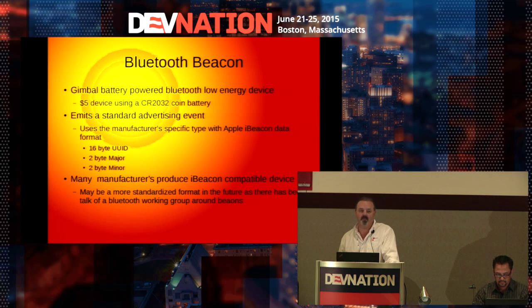You can also take a look at what the format looks like with a Bluetooth low energy scanner that TI sells. Some of the stuff I did early on was just trying to figure out what exactly was in there and what was useful about that packet format. But essentially it boils down to there's a 16-byte UUID and a major and minor ID. So that's all that advertising packet contains.